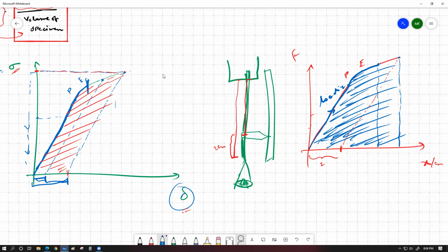Whenever we do unloading, for example, the part that I've represented over here by this dotted line of the return path, let's say we chose to unload the object from this point. Now, when the object will be unloaded, we're going to be slowly taking loads out, and the elastic force is actually working this way. So let me just use a different arrow. The elastic forces are working this way. So if we remove some load, this whole thing is going to start to go slightly upwards because we are removing the deforming force. So in that case, work would be done by the existing force of the system. So work will be given out, or energy will be leaving from the system.